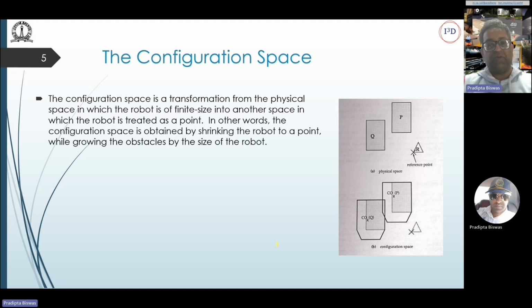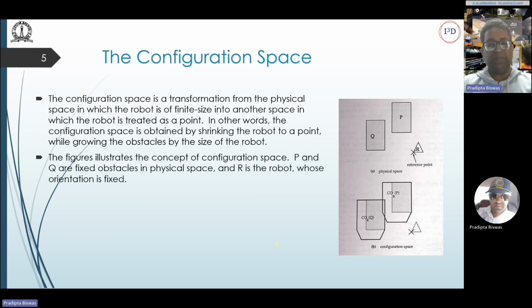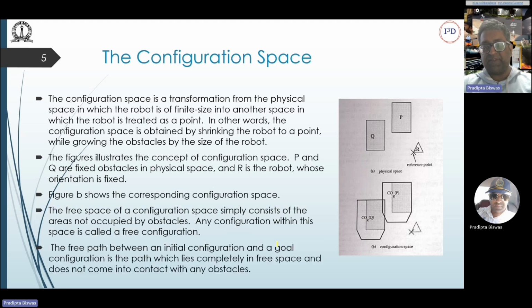So this is a bit of revisiting of configuration space, which is also commonly taught in maths and physics lectures, where we define the space which is defined by all possible configurations of an agent. Here we can also define configuration space of a point or a rigid body. So on the right side you will see some examples of configuration space and how it takes shape based on this triangular robot. And in this lecture, we will actually try to find the equation of these half planes that constitute the configuration space for this triangular robot.